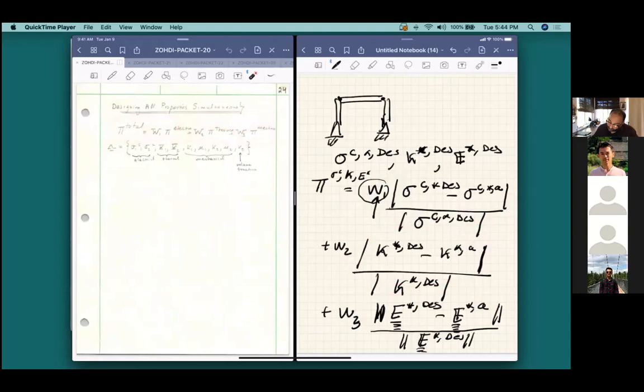Now, what are all of the parameters that are in the system? This is worth reviewing. Number one, we have the conductivity of the first phase, the conductivity of the second phase, the thermal conductivity of the first phase, the thermal conductivity of the second phase, the elastic coefficients. So in this case, if I assume it's isotropic, the bulk modulus of the first phase, the shear modulus of the first phase, the bulk modulus of the second phase, the shear modulus of the second phase, and then finally, how much of the stuff do I add in there?